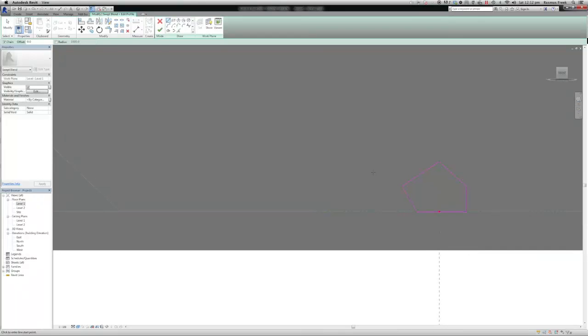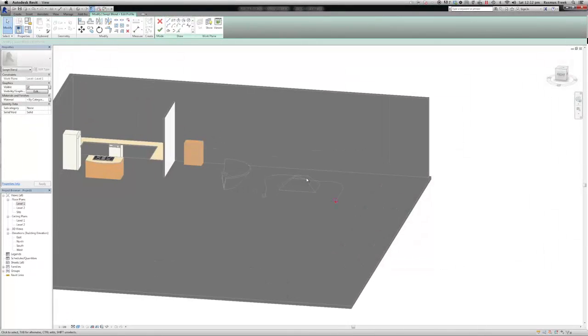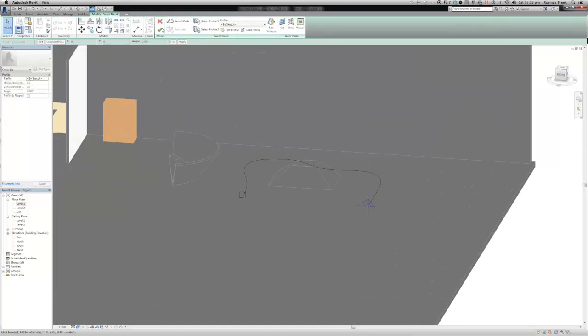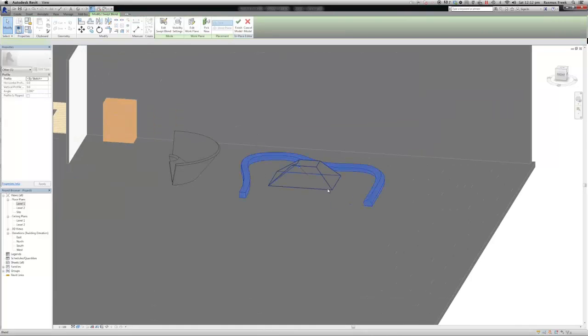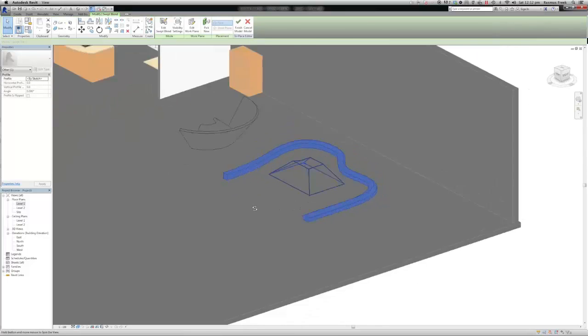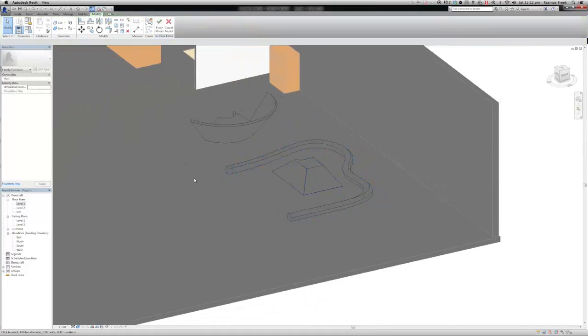When both the end shapes and the path have been made, click the green checkmark to finish the form. This tool blends two forms together over the path. You can also give this form a material. Remember that all shapes we have made can also be made as void forms.